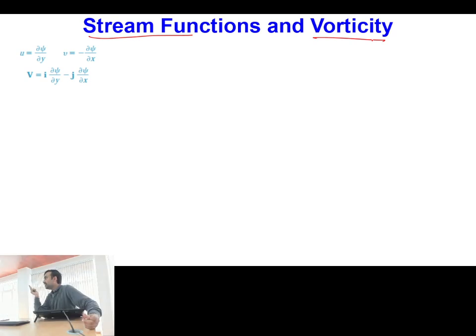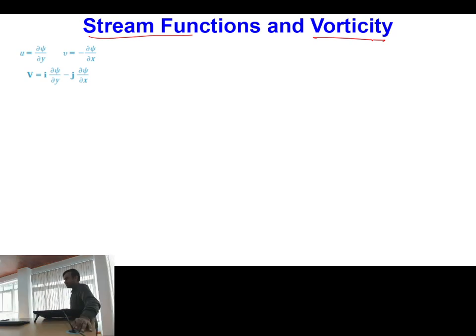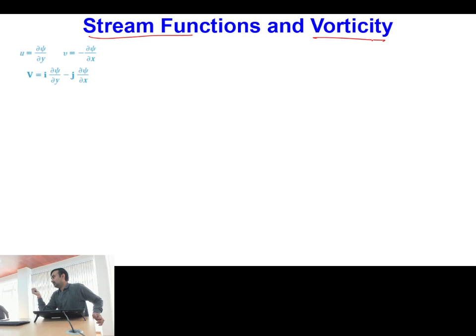So only I need to solve a momentum equation, and whenever we solve the momentum equation, then also my two variables u and v, like component velocity in x direction and component velocity in y direction, can be written in the form of a single variable, which is a stream function. Okay, so that is the advantage of using the stream function. So first thing is, our majority of these spherical situations will be of axisymmetric nature, which can be approximated as a two-dimensional flow situation. And for two-dimensional flow situations, we have this important advantage, that continuity equation, if we use stream function, is by default satisfied, and the momentum equation, which is involving variables u and v, these are clubbed together into a single variable psi. Is this one clear?